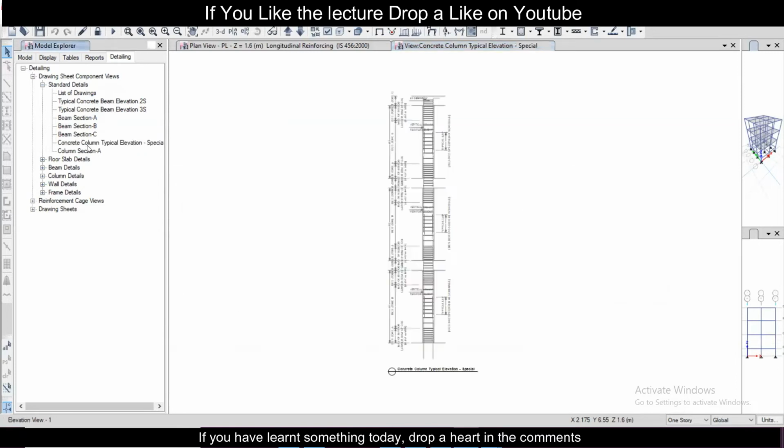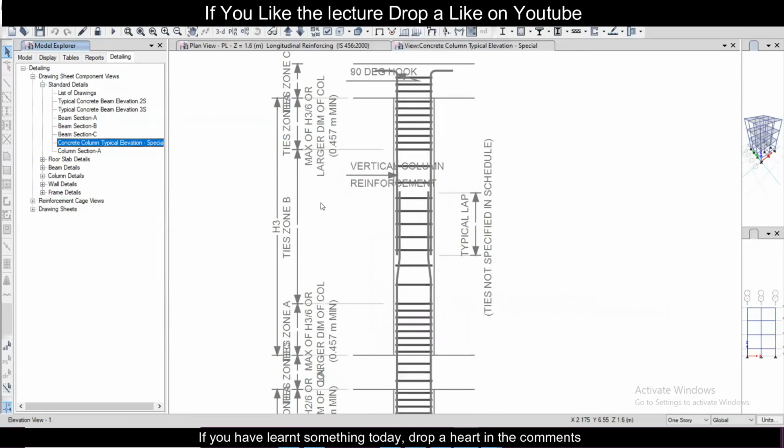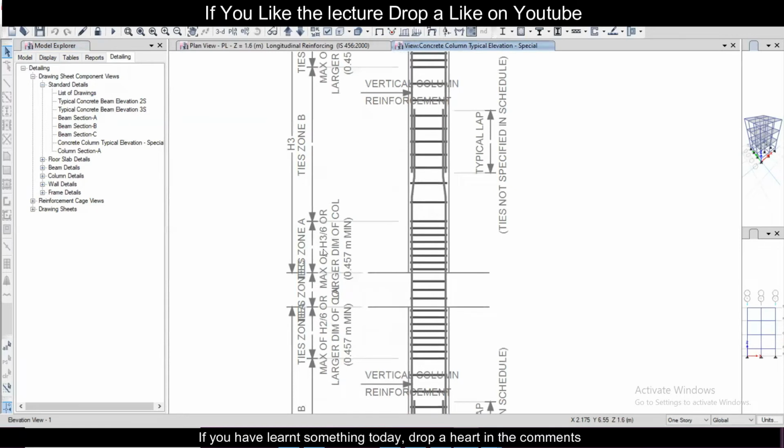So similarly, we have this in the case of columns as well. As you can see, there are three zones here: zone A, again zone A, and zone B. As you know, in zone B there is the minimum moment, but near the supports of the columns there is a maximum moment. So it's generally L by 6, or the maximum of H3 or L by 6, or, as it's written here, the larger dimension of the column. It is L by 6.